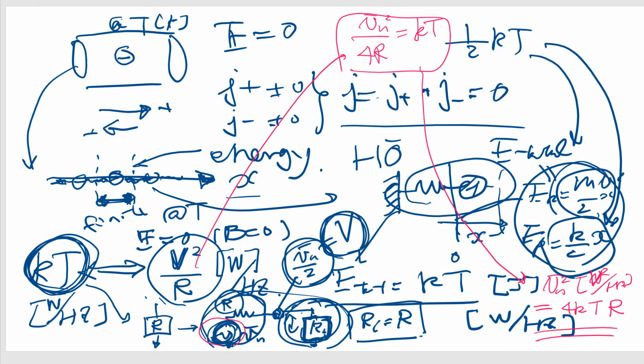Now we have reached the goal. Energy kT, distributed to the kinetic and potential harmonic oscillator movement of the electron in a metal in one dimension, produces the noise, and at maximum the external device catches the noise with the voltage V equal to half Vn of the noise voltage RMS, which means RMS on average.